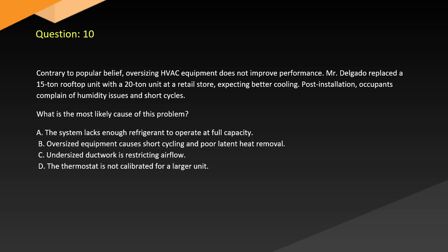Question 10. Contrary to popular belief, oversizing HVAC equipment does not improve performance. Mr. Delgado replaced a 15-ton rooftop unit with a 20-ton unit at a retail store expecting better cooling. Post-installation, occupants complain of humidity issues and short cycles. What is the most likely cause of this problem?